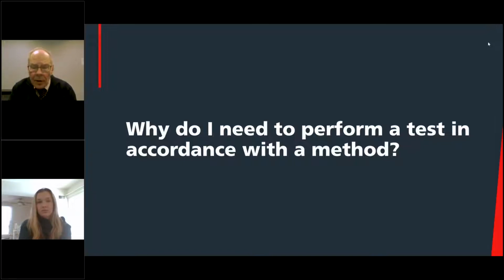The problem with ground testing is most electrical testing is done on a discrete item, a motor, a circuit, whatever, so you know what it is. With a ground test, you're connected to the entire planet. And so that introduces a variable that you don't have in most electrical testing, and you have to deal with it. So if you just ran leads out, and this is fairly commonly done, and it's a little bit risky, if you just ran leads out and put probes in the soil and took a measurement, yeah, you might get a good measurement.